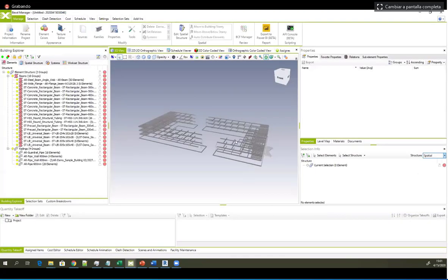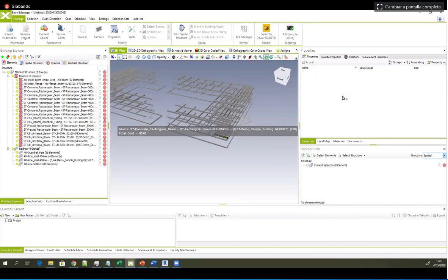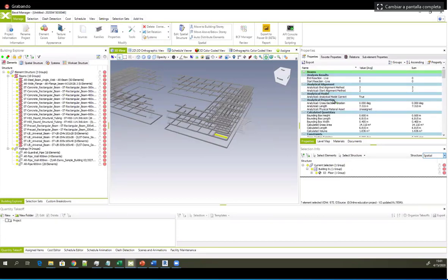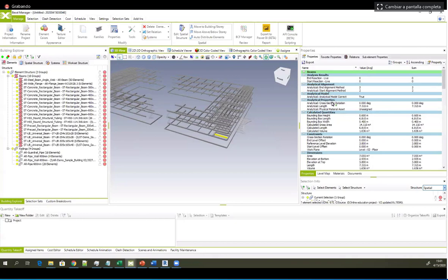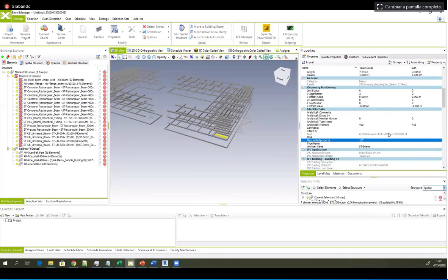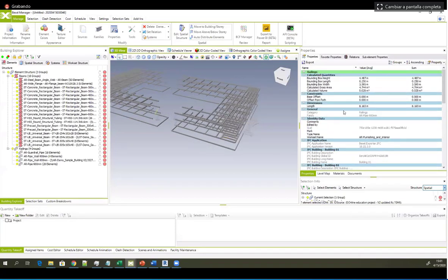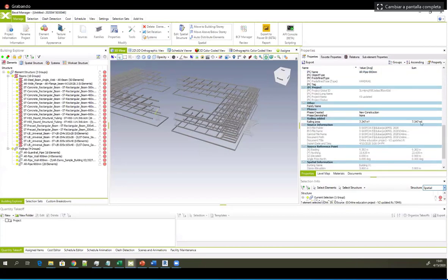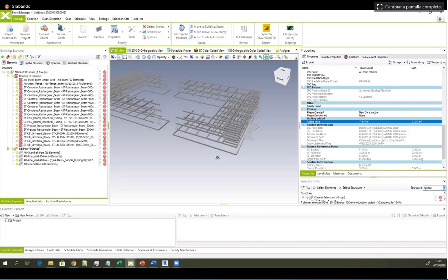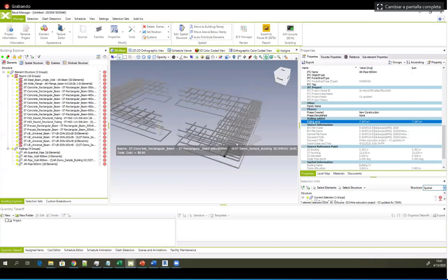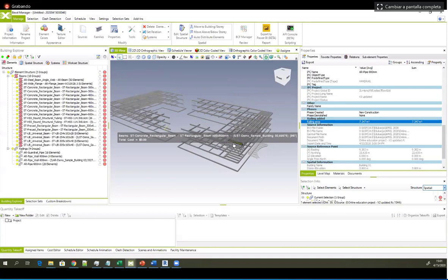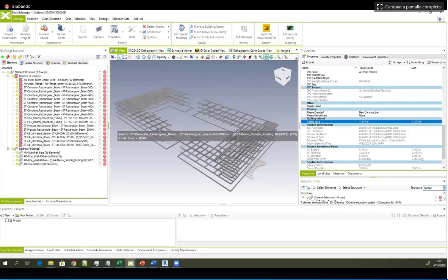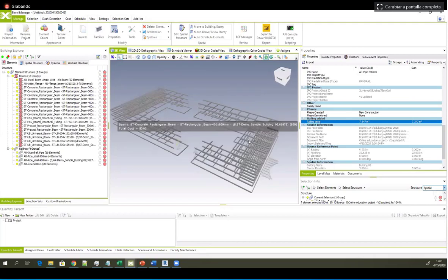So these are exported elements. If we select any of these beams, you see all available information, and also within the identity data, we're gonna have the new edit property with these properties also for the railings. We're gonna get a new property group, which is railing added, with this information also saved. And also when you create your cost information and scheduling information, all this information is also saved if you export IFC file formats.